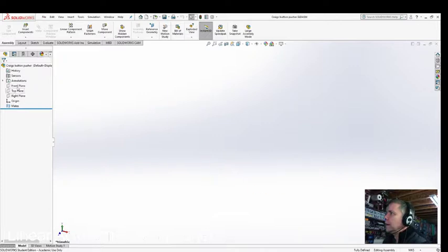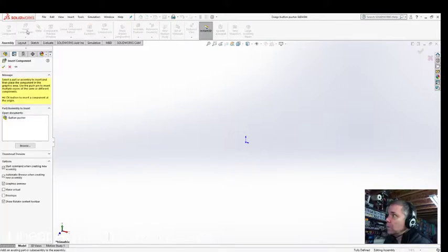Okay. Now, one thing I'd like to do is I'd like to see my origin. So I'm going to go to hide show and choose origin so I can see the beginning. Now we're going to bring the parts we need in. So we're going to insert the components we need. To do that, we're going to browse, and I'm going to find all the parts we need.